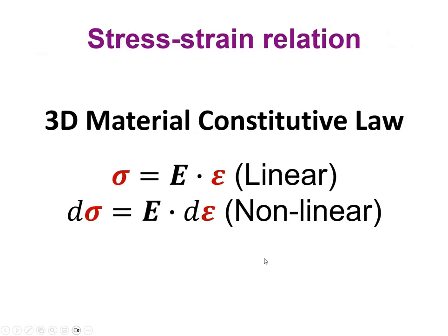When we go to the three-dimensional space, of course, things become more complex, because we have 9 components for the stress tensor, as you remember. So this sigma in here will be the stress tensor now. So if the relationship between the stresses and strain remains linear in the three-dimensional space, we are going to have the stress tensor equal to what is called the elastic tensor, multiplied by the strain tensor epsilon, that we are going to study in more detail in a few minutes.